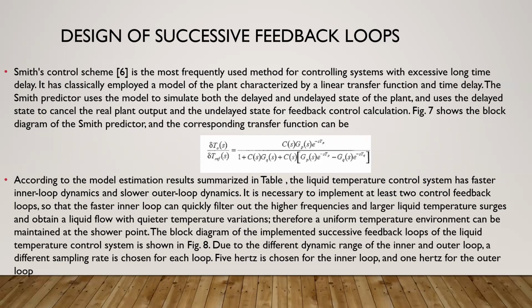Here we can see the relation between the output and the reference, which is equal to C(s)G(s)e^(-sTp) divided by 1 plus C(s)G(s) plus C(s)G(s)e^(-sT).